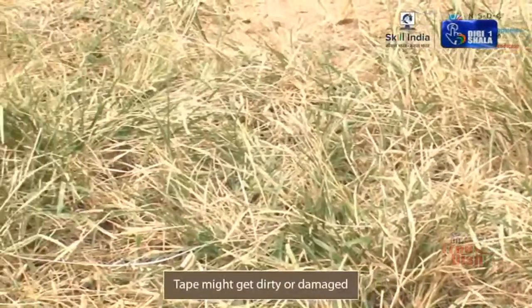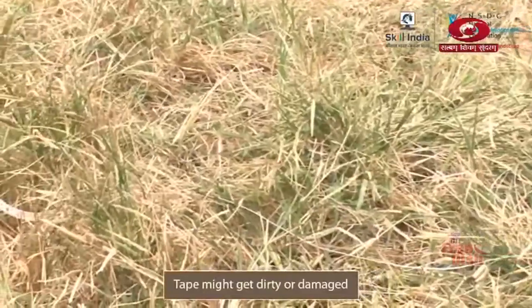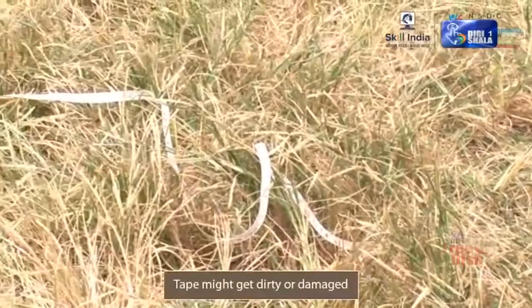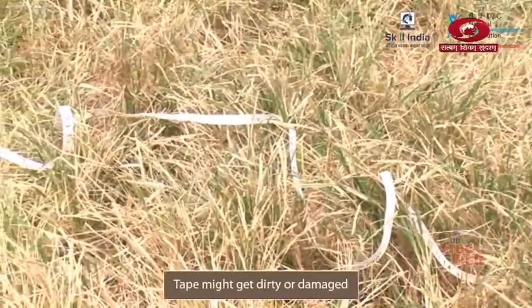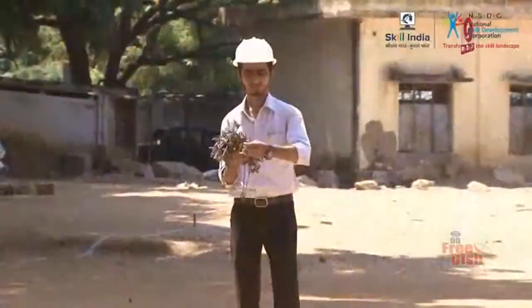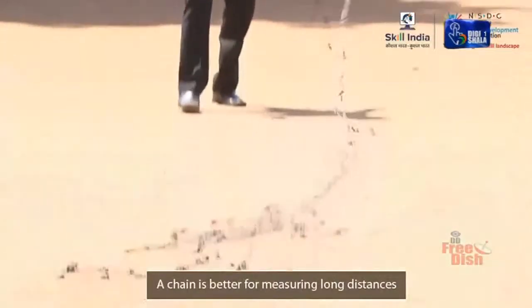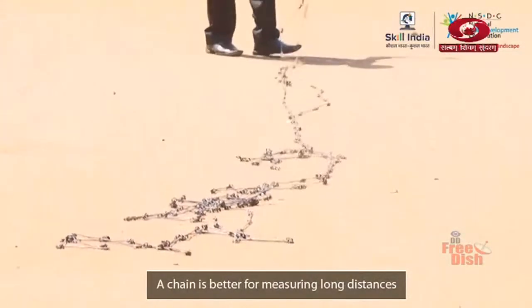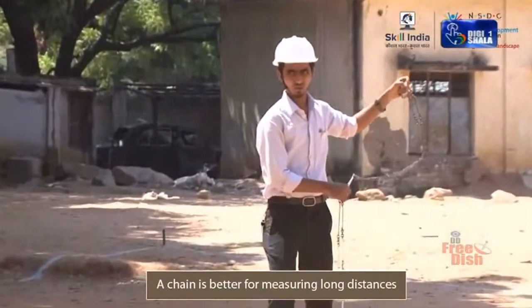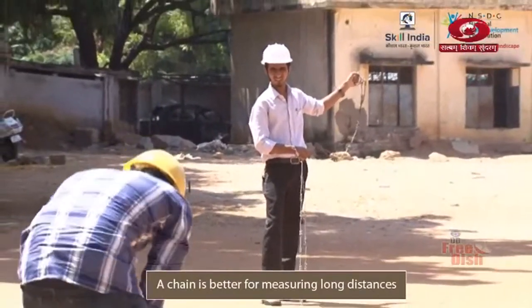Also, if the site to be surveyed is rough terrain, full of stones, mud, or grass, then the tape might get dirty or even damaged in use. In such conditions, the chain is a better option, as it is a metallic object of a fixed length which can be moved along the ground quickly by throwing it around or even dragging it.